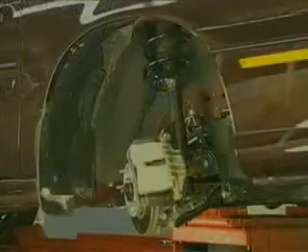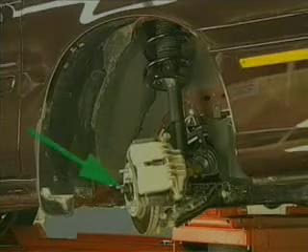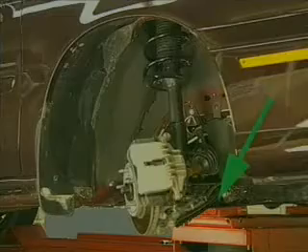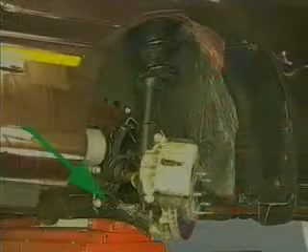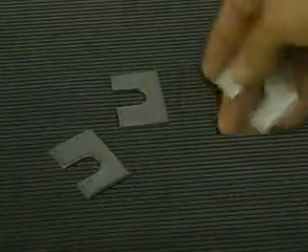Prior to attempting a caster adjustment on a suspension that does not have a factory adjustment, inspect the suspension for bent or damaged parts and replace them to correct out-of-spec conditions. Adding and removing shims on the upper control arms will correct both camber and caster on most rear-wheel drive cars.